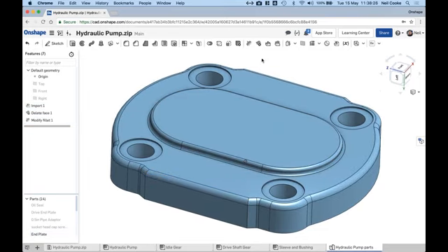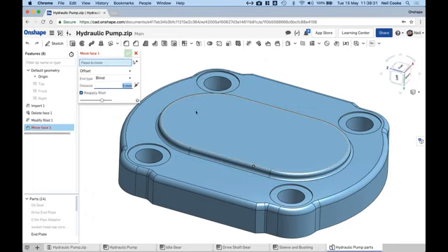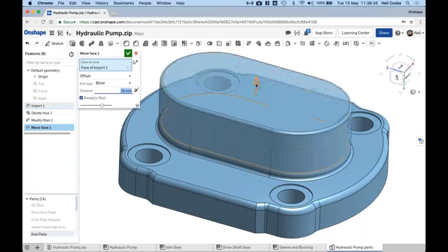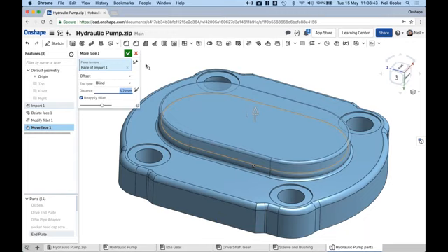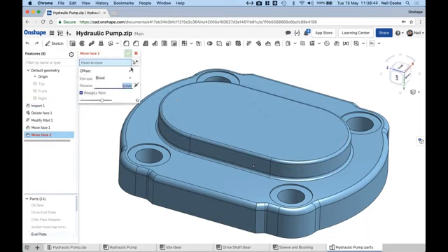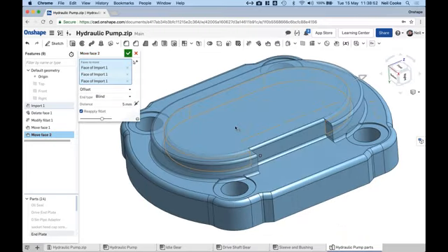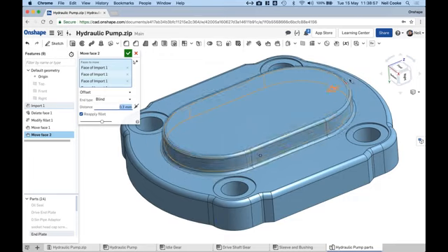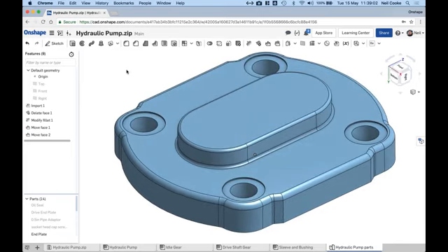We can also do things like move face. Now, with move face, the idea is that you might take a piece of geometry, say just picking that top face there, and it will automatically pick those fillets and allow you to move them. So that will give you the option to make quick changes. You can move by offsetting, translating, or rotating. So again, if you needed to change the size of this thing, we're just going to pick all 4 faces and then modify those sizes, either bigger or smaller. So you get to see all this capability to be able to modify a design.